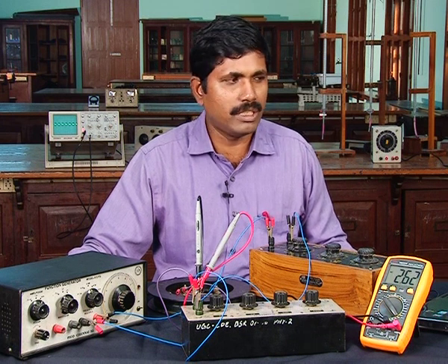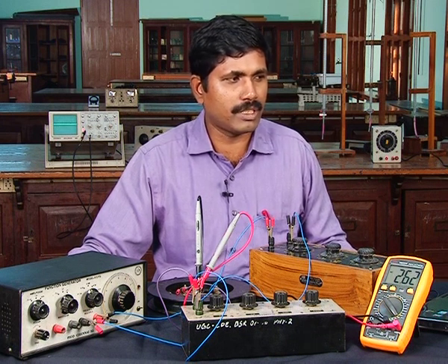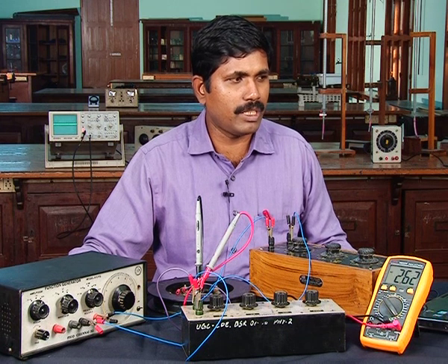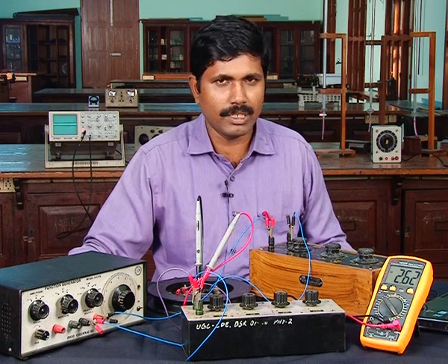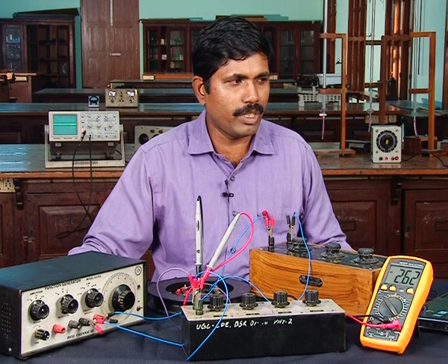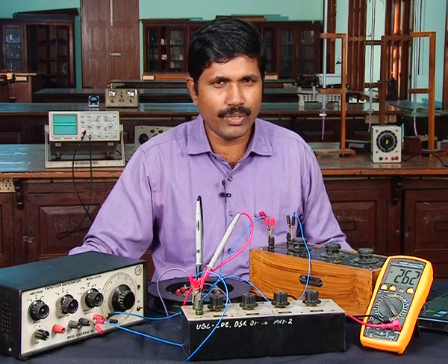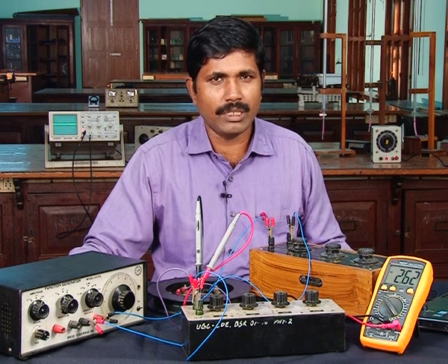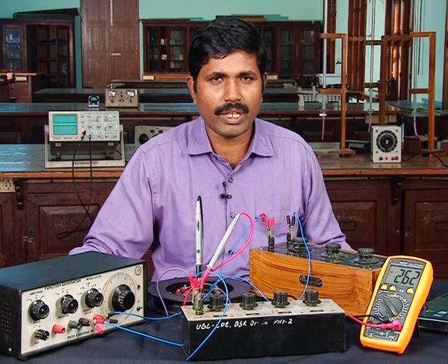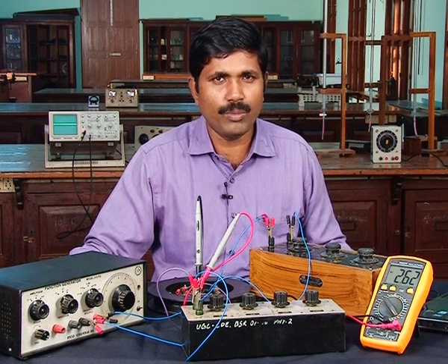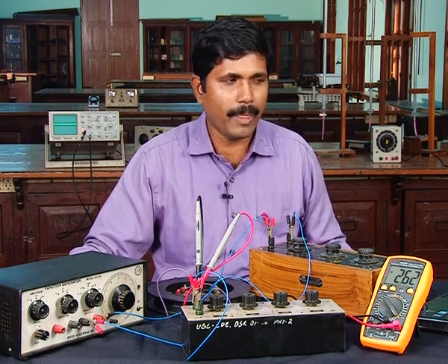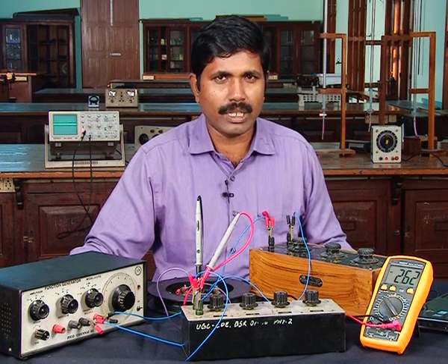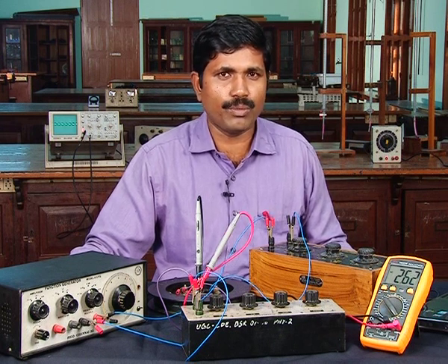This is how an LCR circuit can be studied and various parameters can be calculated. Thus, in this experiment, we calculated the resonant frequency of the circuit. We got that as 1 kilohertz, and the bandwidth of the circuit, which is a wider one, and the quality factor of the circuit, whose value is very low, so the circuit is classified as a wider bandwidth circuit.